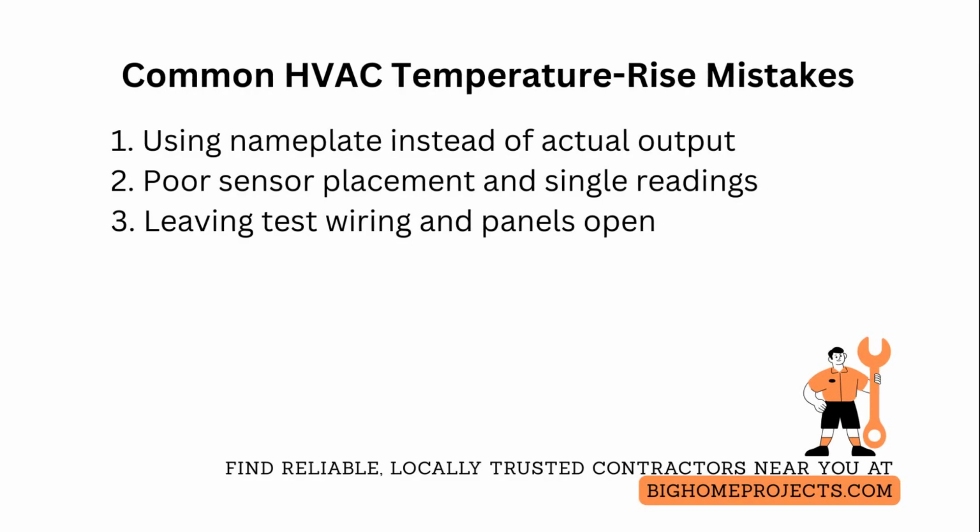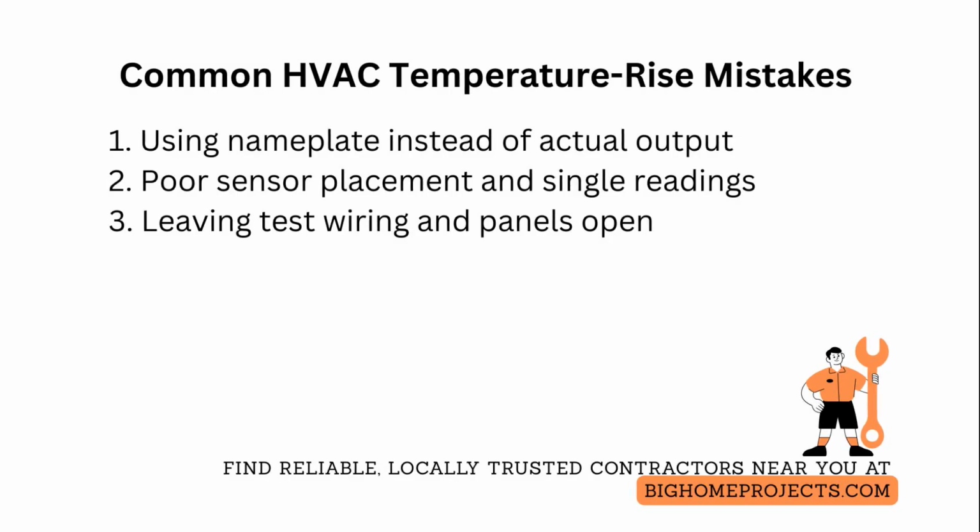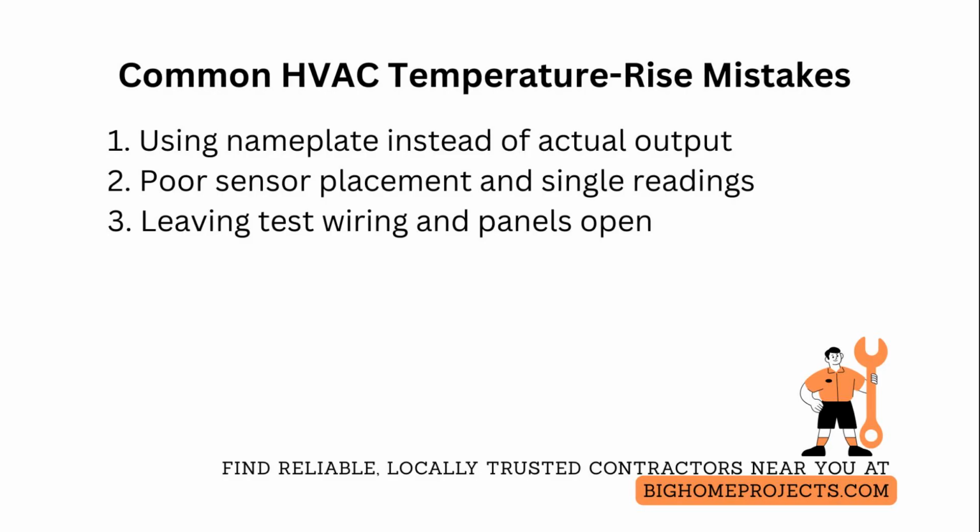One of the other typical problems is leaving test wiring, temporary jumpers, and open panels in place after the test, creating safety and control sequence faults. Fix this by following a strict reset checklist.